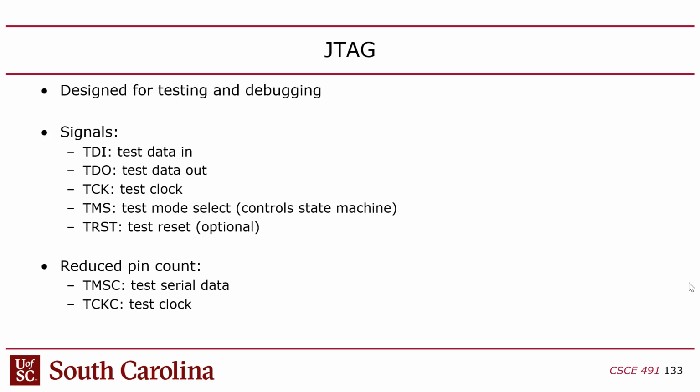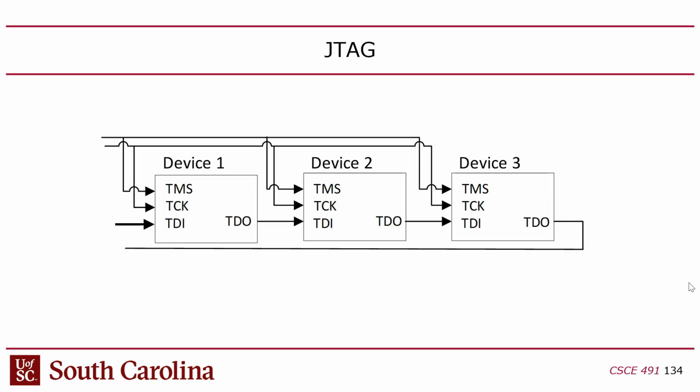Okay. So anyway, how does JTAG work? Well, JTAG's a pretty neat protocol. The way it works is a single master, multiple slave. And it basically works like the SPI daisy chain approach. The idea is that the master sends data out, and it gets cycled through all the slaves. So you have this thing called test data in, which is basically equivalent to MOSI, right? Test data in goes into the device, and then test data out comes out. That's equivalent to MISO, right? So you basically have MOSI coming in, MISO coming out, except in JTAG it's called TDI and TDO, right?